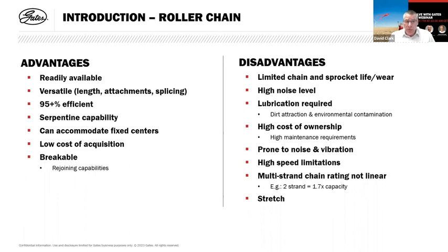They are versatile. You can change the length, you can add attachment, you can splice them together. They are relatively efficient when new and when maintained. They have the opportunity to run on serpentine drives. You can run counter-rotating drives, and you can run drives with multiple shafts with chains. They can accommodate fixed centers. They're relatively low cost, and they are breakable. You can take them apart and rejoin them.